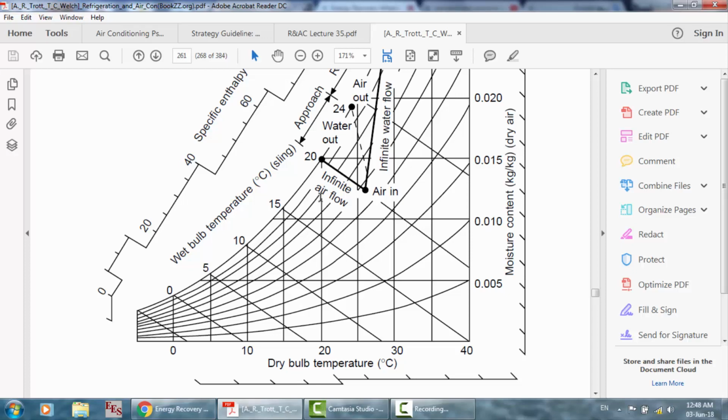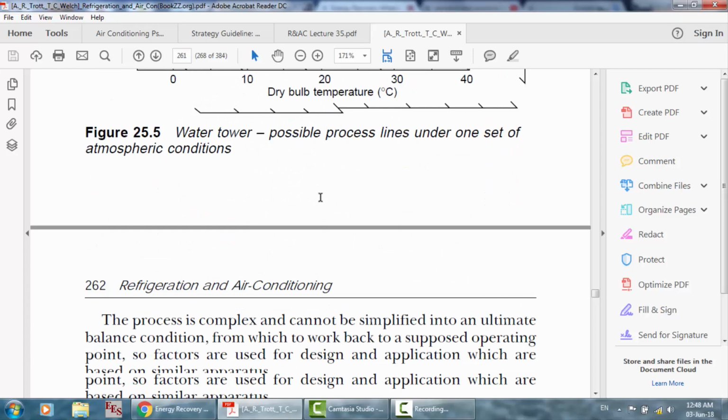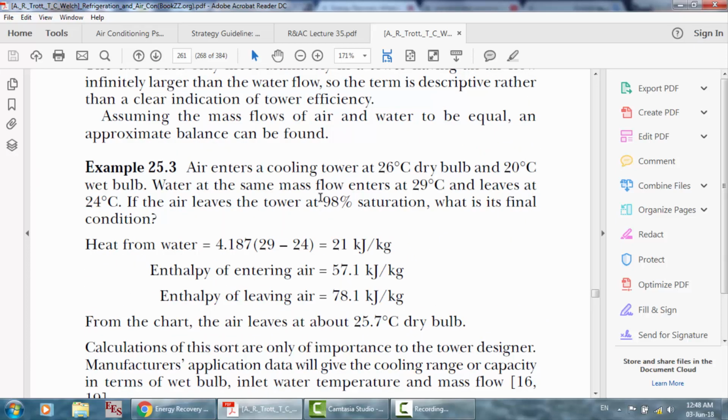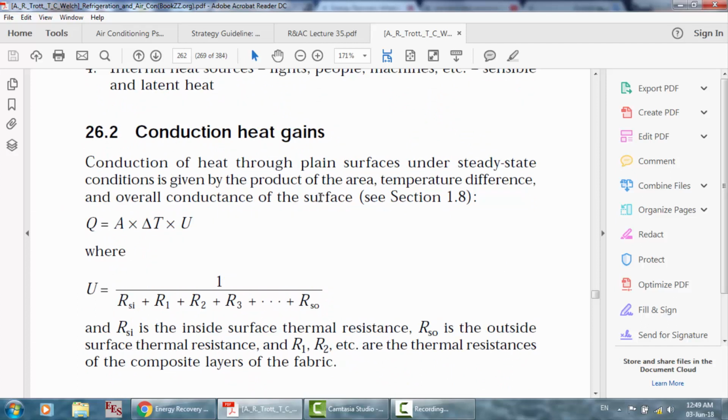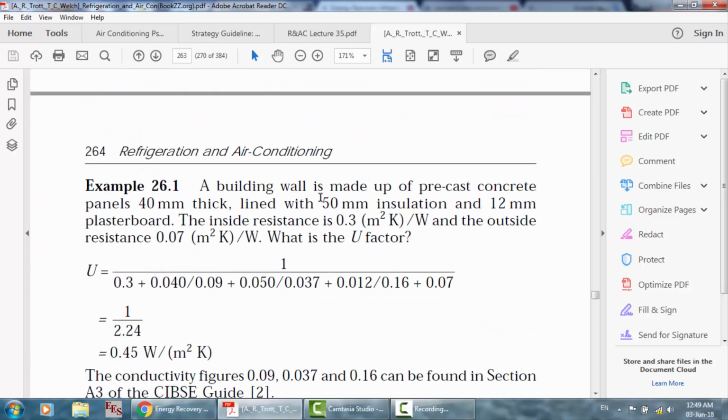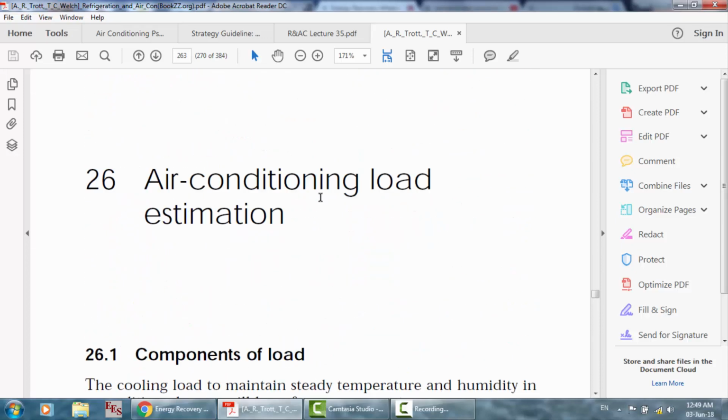Also, if the lighting, occupancy, or appliances are too much, or if they help you by adding heat to the system, this decreases the amount of air that's required for ventilation, due to the equation that we talked about.